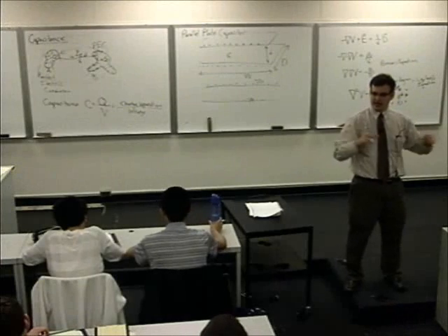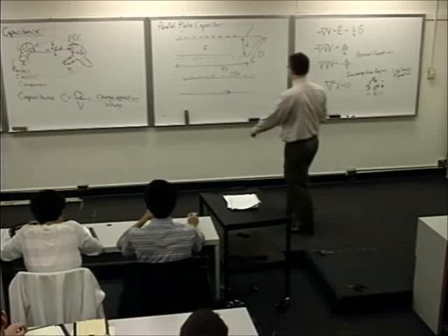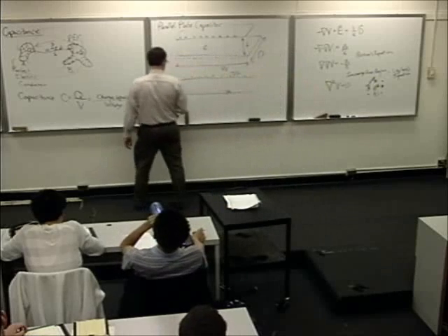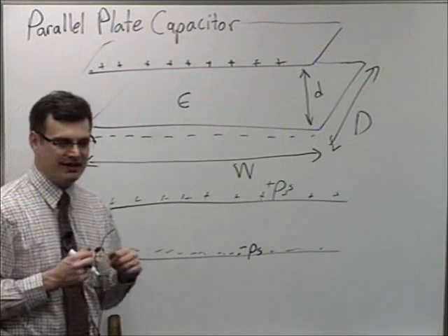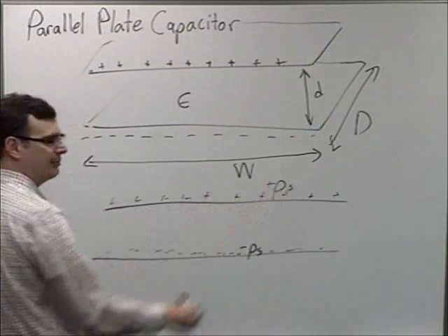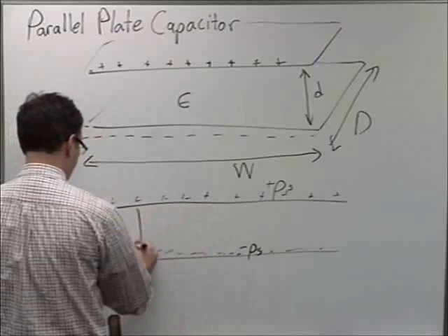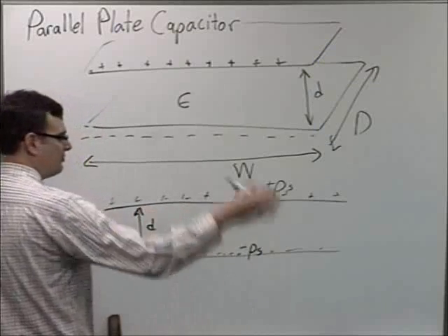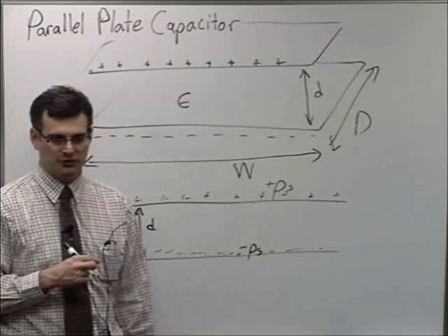The charges tend to spread out because they're mobile on a piece of metal. And so if we look at this system, how do we go about modeling this? Well, like any good engineers, we're going to make assumptions. We're going to say these are really big plates compared to their separation distance d here. In fact, they're going to be so big we'll call it infinite. And then we'll kind of fudge the solution afterwards, right?